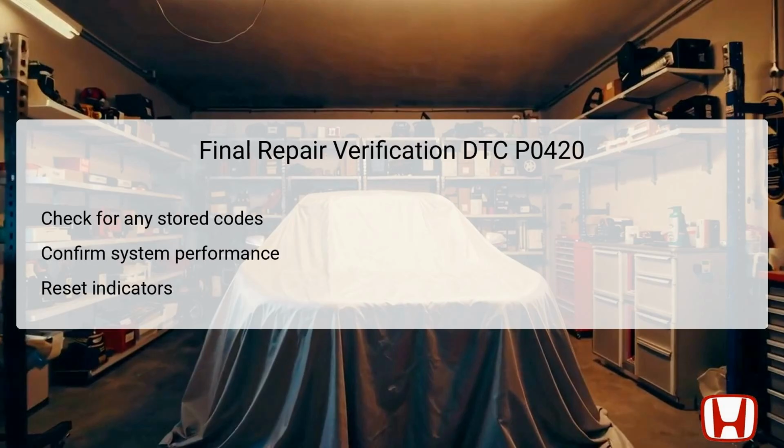The final repair verification phase involves ensuring that no new or existing error codes remain in the system after completing all repair procedures related to DTC P0420. Utilizing the HDS tool, the technician should perform a comprehensive scan to confirm that the codes have been cleared and that the check engine light is no longer illuminated.